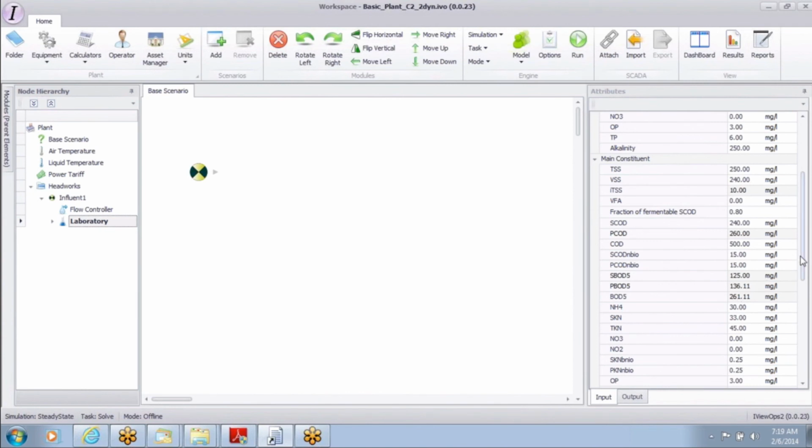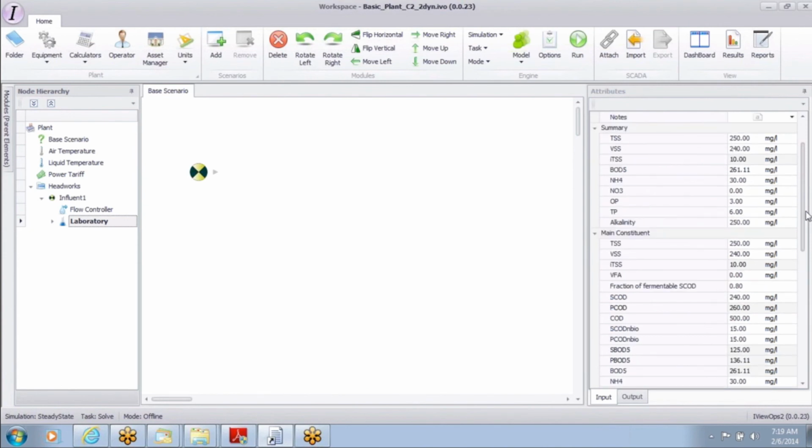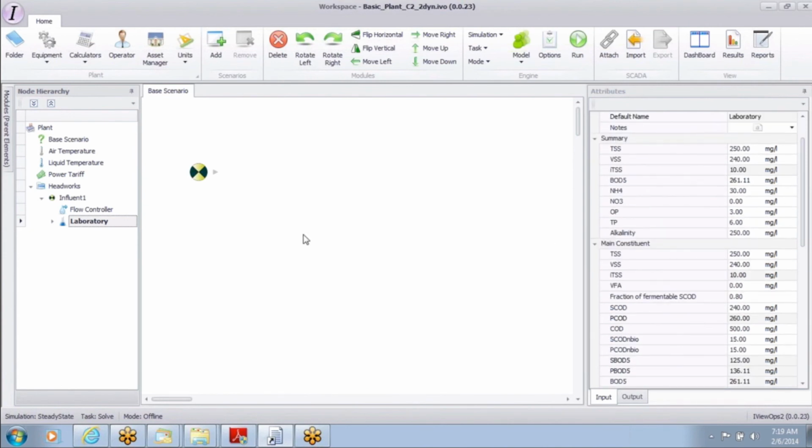What is more important is that from your BOD data, you get to a COD data, you enter your COD data, and then you can go back and change that COD to BOD ratio. We will make some changes in the model down the road to make it easier, but that'll be a few months down the road. You'll have another part of this menu where you can check all this right on this screen.